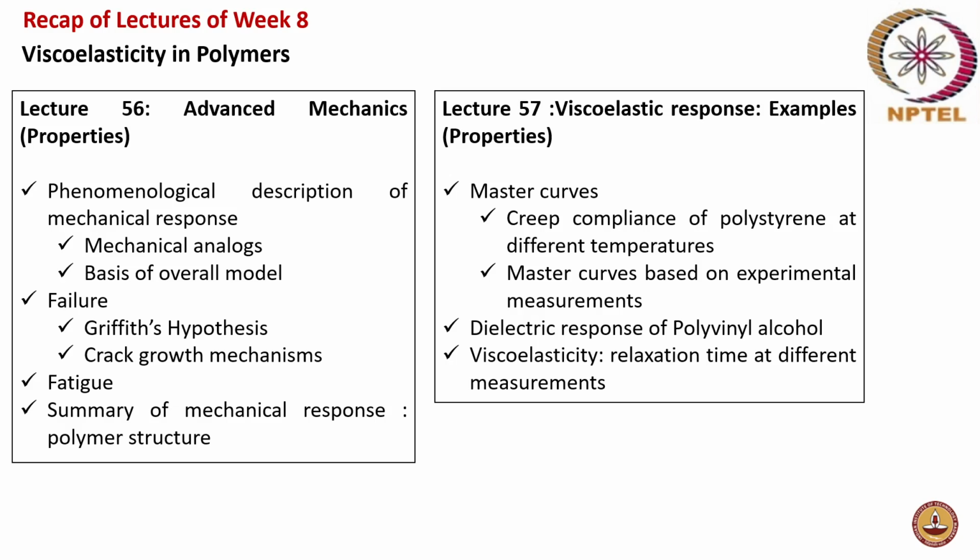Based on time temperature superposition, you can prepare master curves, because, for example, a polymer can have a service life of 25 years, right? So you have to know how, for example, your creep compliance behaves for 25 years. But in an actual practical scenario, you cannot keep conducting tests for 25 years and after 25 years say that this material has that compliance, or that it does not have enough compliance to withstand 25 years. For practical purposes, you do not have that long a time.